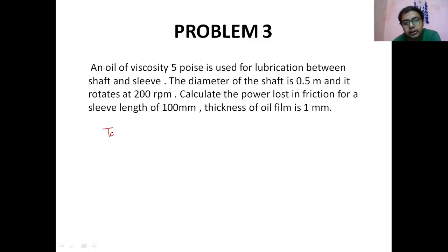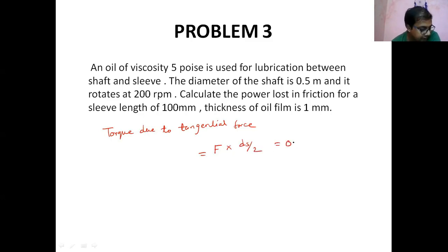Torque due to the tangential force. And what is that value? The torque due to the tangential force is the shear force into Ds by 2. The shear force already came as 0.41 into 0.5 by 2. It will come around 0.1027 kilonewton.